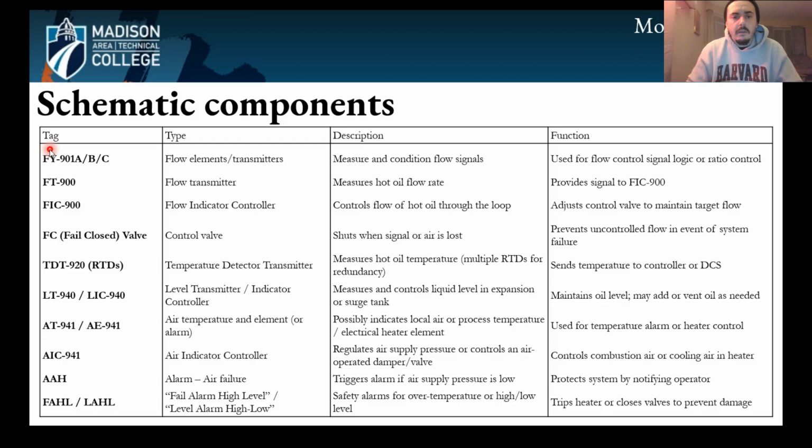The three Fs here, excluding the FC, the three top Fs here, are part of that flow control system. They all basically decide how much hot oil gets sent through that heat exchanger. FC, we saw, that's the two valves. Those are both fail closed valves.